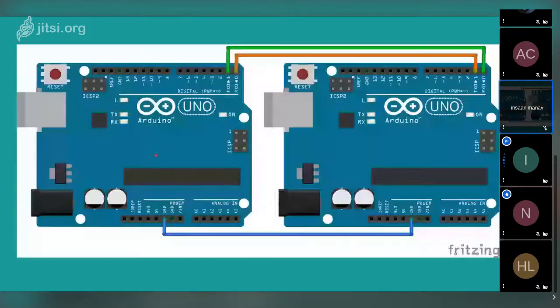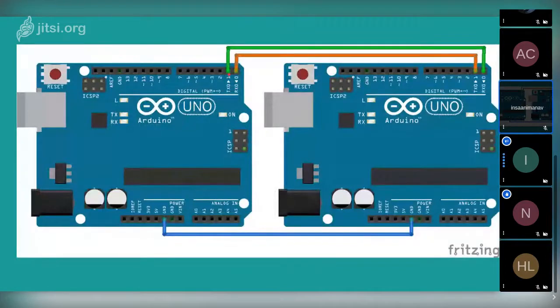So let's discuss how this works specific to an Arduino. In Arduino we have these TX and RX pins right here, which are 0 and 1. A good thing in Arduinos is that we have a single USB port for both serial communication to the computer, and this port is also used for powering.